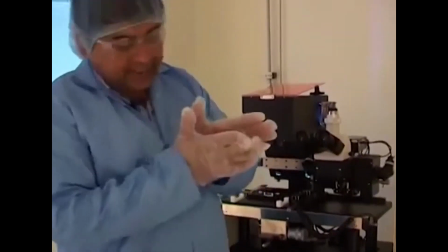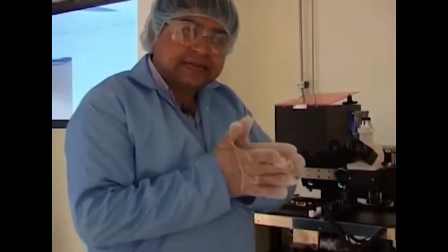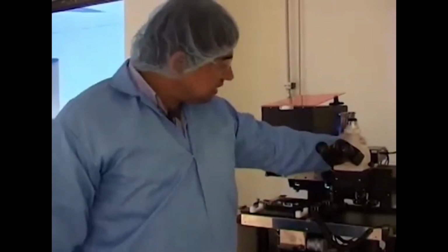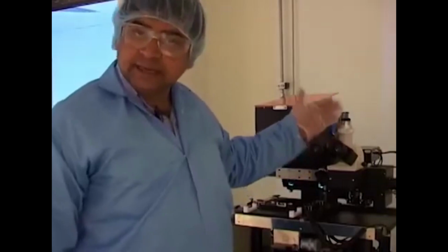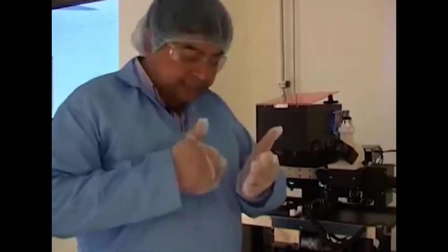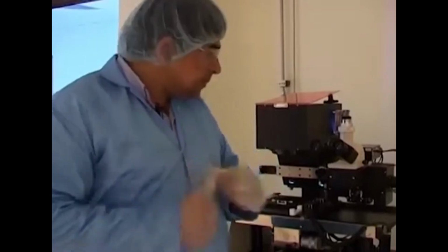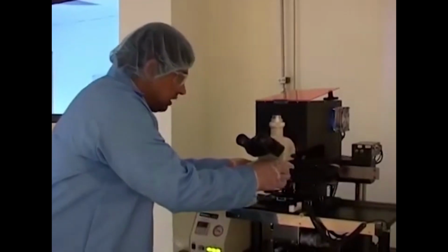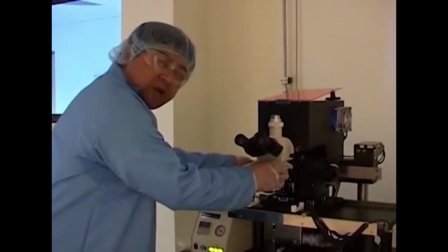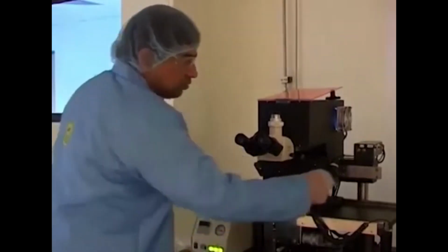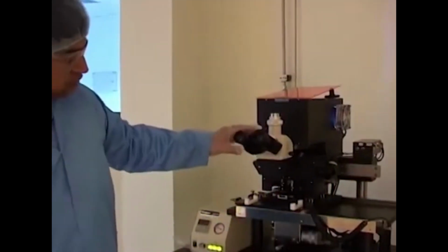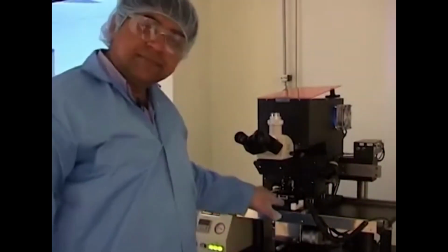The idea is that the wafer has to be Z displaced so that it can come in contact with the mask surface, and for doing that we also use this scope, this microscope. There is a small red light beam which is used for the purpose of seeing whether the wafer is really touching the mask surface. So in the first stage we move this microscope, the scope stage, all the way to its position here above the mask, and then there is a small lock here which we use for locking. There is also a control here where we can turn on the red light, which is now focused onto the mask and the wafer.